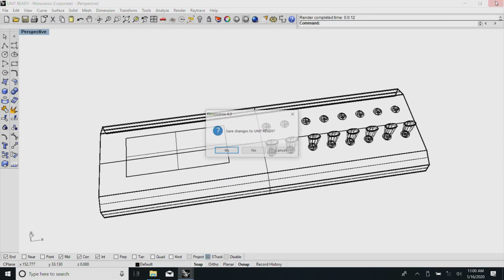Now, come to the point of saying I need to have an enclosure which holds this. So, in the case of that so called 19-inch rack, we already have all those 19-inch rack elements, and probably if you dimension this properly, you can make it as a 2U or 1U also. If you make them a little close together, you can make it within that 45 mm, which will make a 1U. If you make it the next, usually 88 is available, then it keeps on going like that. You have 132 and so on. So, more of them we can make.